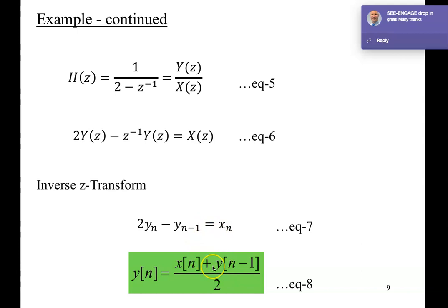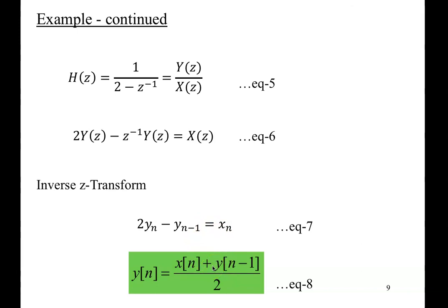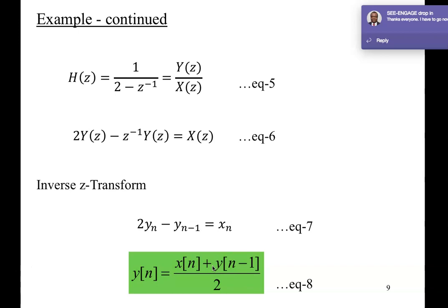So in this case, for any time instant, if you just imagine in your head, you have time sequences. So you have different interval times for the computer to come back and do the calculations. At any particular time, because they are divided into different sections, you can take in the current input, asking the A to D converter, I want a value now for your input.